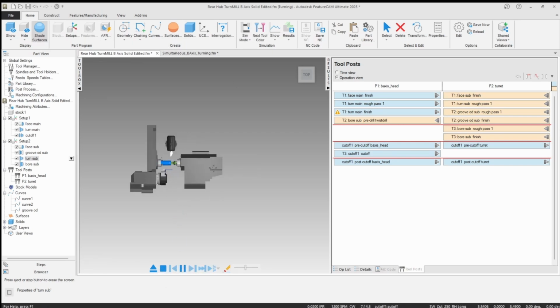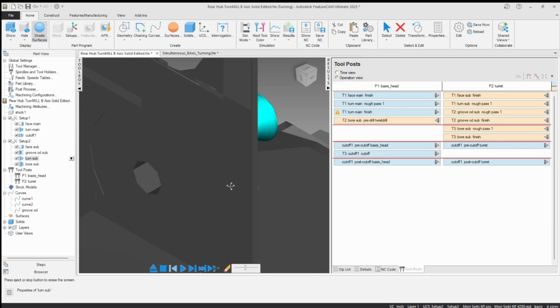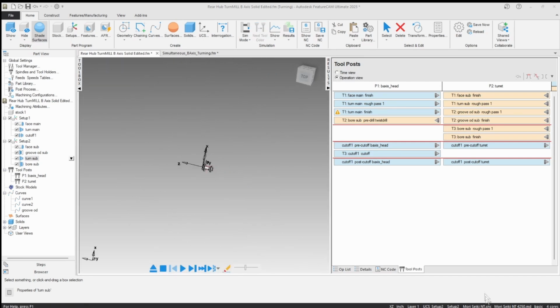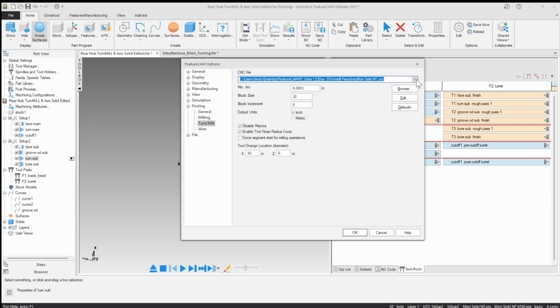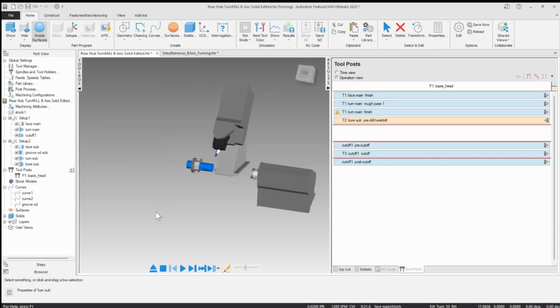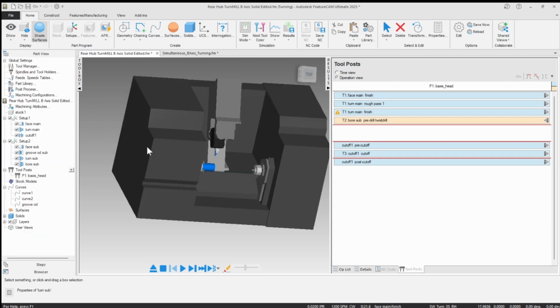So the first time through, it's empty. That's why we were seeing the motion. So you can see that this is happening really fast, I know. I'll go ahead and zoom in on this so you can rotate around. Now, just so you know, if you have a little more complicated machine design, you can actually hide components. So if I hit the select arrow at the top, I can actually hide this cabinet, I could hide doors, I could hide any of those, and in order to get those back, I can hit show all and bring them back.